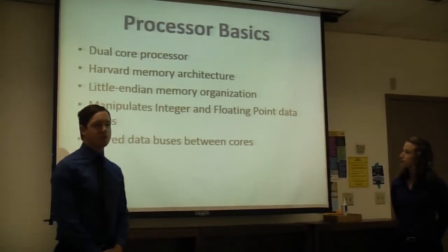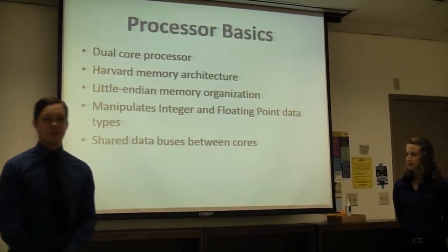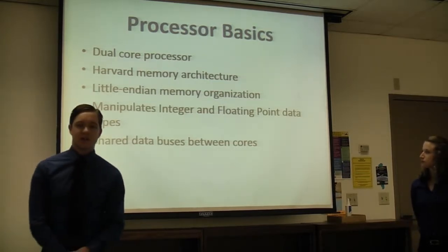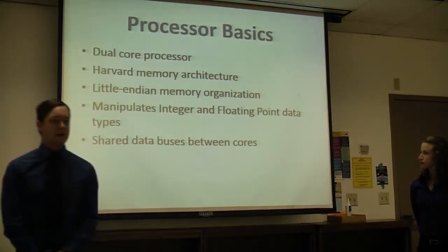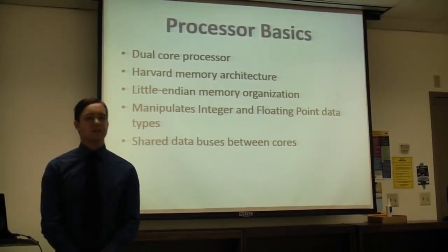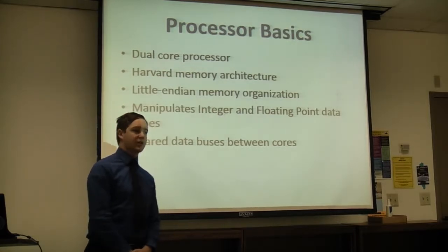So the basics of our processor: we have done a dual-core implementation of this processor. We use Harvard memory architecture in little endian format, as well as a shared bus that shares data among multiple cores, and we manipulate both integer and floating point data.